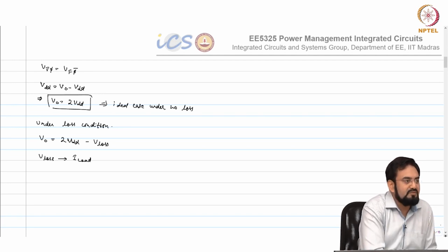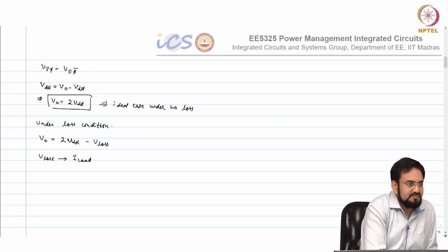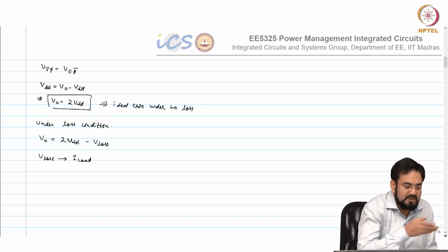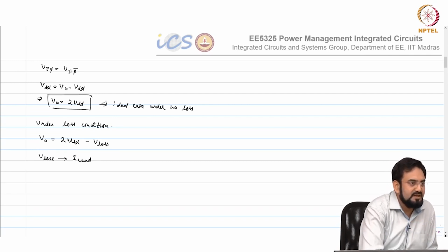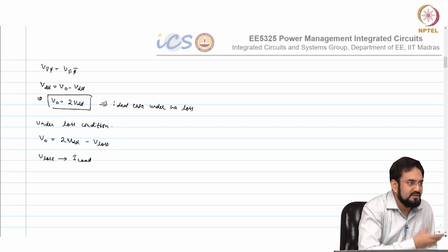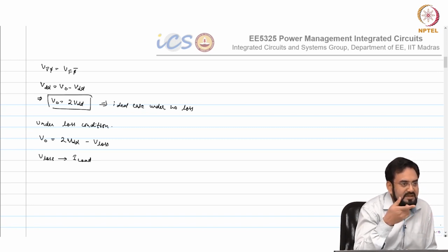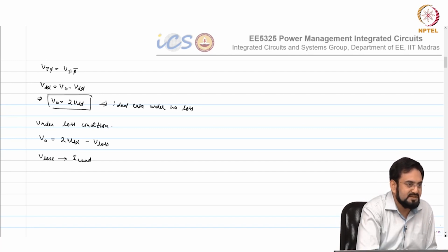So another application, let's say I want 1.5x. So one possibility would be you do a 2x from the charge pump and put a buck after that, and it will give you 1.5. And if you guys remember, what is the problem in the boost, it's a bit slower because of the right half plane 0. In this case you can easily get rid of that right half plane 0. So that's one application.